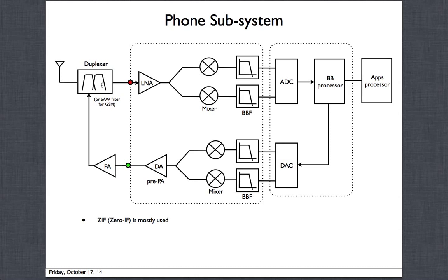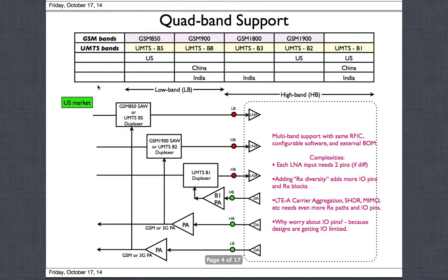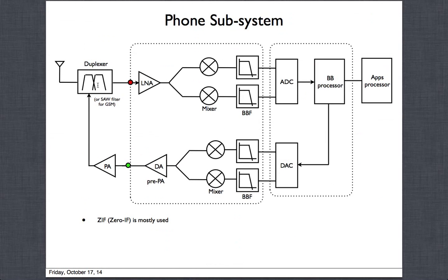So this frequency separation is not a lot. I think I have a table later on. They're not very far away. For example, if this was band 1, with things happening around 2.1 gigahertz, the separation between the TX and RX is only 180 megahertz.